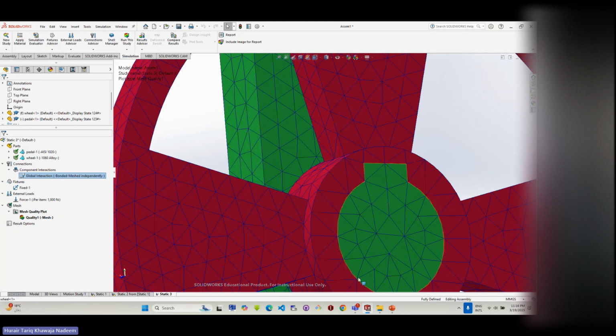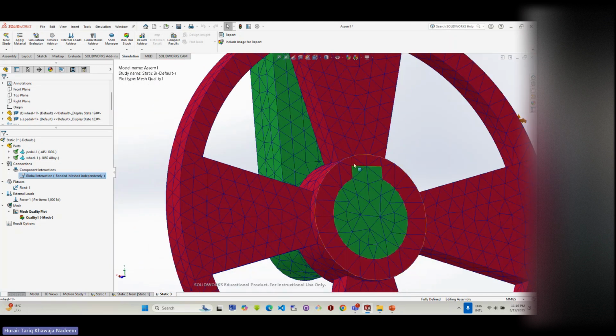And look, the nodes are talking to each other. They are aligned. Can you see? All the nodes are aligned. These are the corners. The corners are actually talking. You will never find that a node is actually somewhere in the center, okay? They all are talking to each other. And you will never find a triangle where half of it is over here, half of it is on the other side. Now, go and run a study.